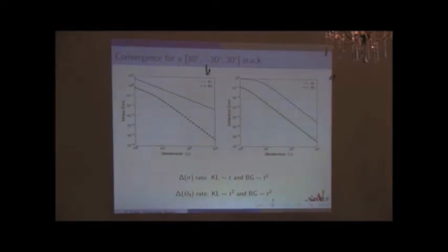Okay, so I would say that asymptotics are nice, but seeking higher convergence rates does not always make sense, especially in terms of practical applications, because we don't actually deal with slender structures. And here precisely, I don't pretend that it converges faster. Actually, it does not, but it's much more interesting to use the bending gradient theory compared to Kirchhoff-Love plate theory in that case.